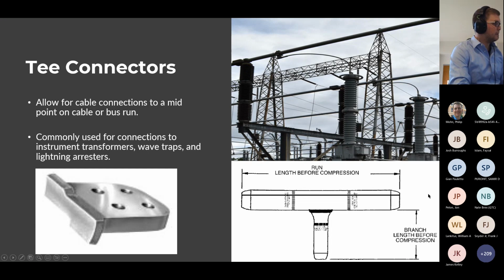You'd have your main run here, and let's say you have a pigtail coming up above grade to then land on the structure leg. Similar with the compression style, this black line here is a piece that you can take off. You lay your main cable run in here. You hammer that top piece back on. You push your tap pigtail inside on this part, your tap, and then this shows you the lines of where you would crimp.